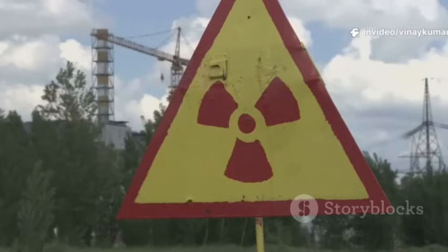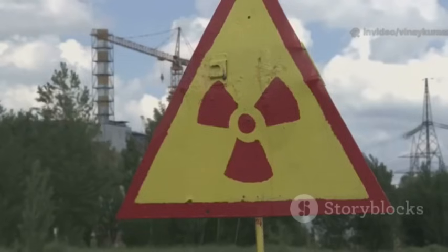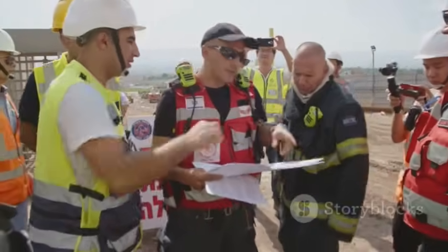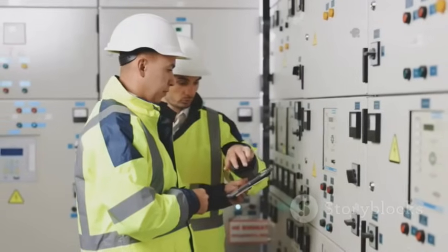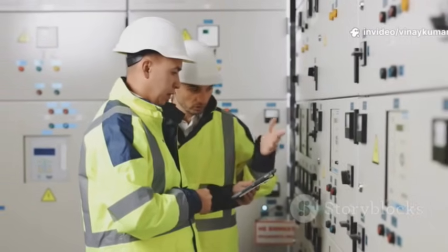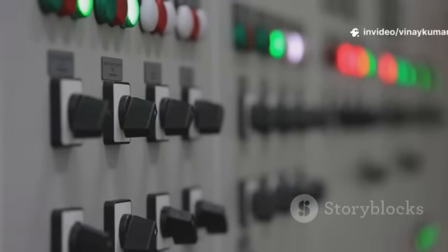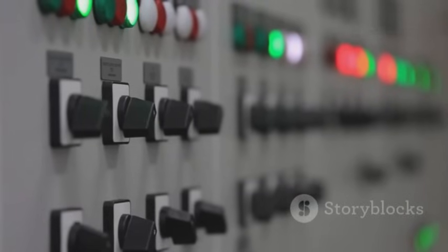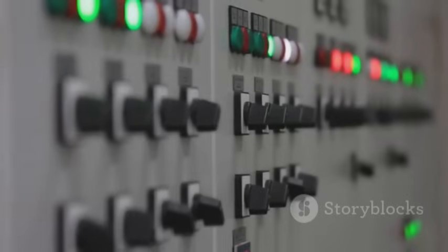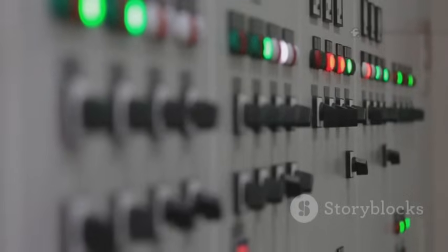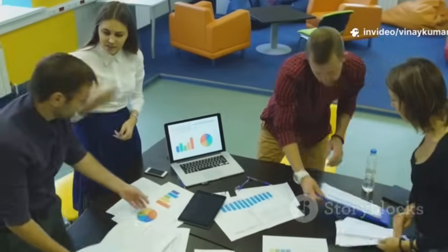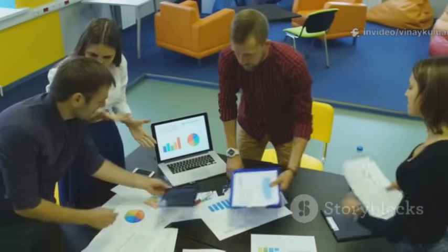The PHA must address the hazards of the process, identify any previous incidents that had a potential for catastrophic consequences, and pinpoint the engineering and administrative controls in place to manage the identified hazards. It looks at the consequences of failure of those controls. What happens if our high-pressure alarm fails? What if the operator doesn't follow the procedure? This isn't just a paper exercise, it's a critical thinking session that results in a prioritized list of risks.